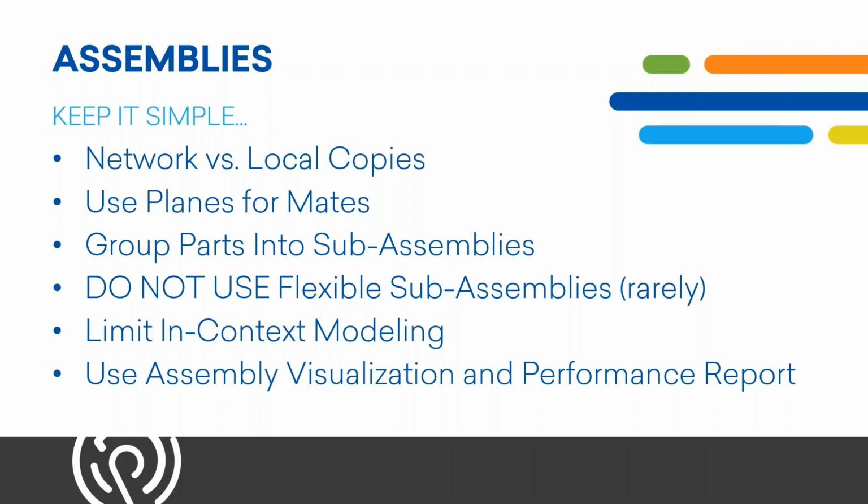So you're either going to shoot for mating to the original planes, or you're going to mate everything to one solid foundation and object. If things are related to each other, then it becomes kind of a chain, and that chain can be broken or stretched, and that's what we want to kind of minimize. We want to have direct mates that go directly from one subassembly to maybe the main subassembly or the main component of your assembly.